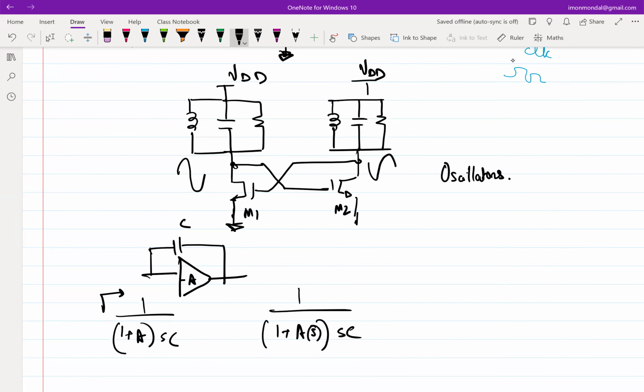No, it is some weird thing. Part of it is probably capacitor. That's why Miller capacitance ironically works only for low frequencies. You can use this configuration to mimic a capacitor only at very low frequencies where A doesn't change. A is constant. If A is also a function of frequency, then it's not a Miller cap anymore. But that's a good point.